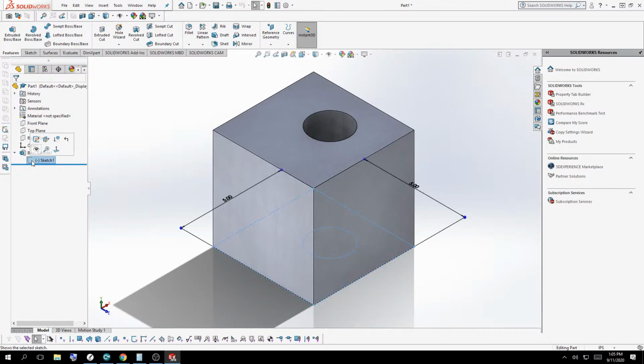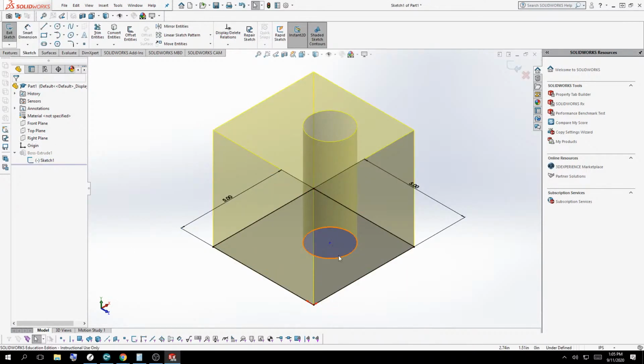We're going to click the icon of the sketch, not the word. If you click the word, what's going to happen is most students kind of end up clicking on this, and then all of a sudden it goes to renaming your sketch. So that's confusing. But to avoid all of that scenario, you're going to click the little icon of the sketch, upper left corner of the Edit Sketch button, and that's how you can get in.